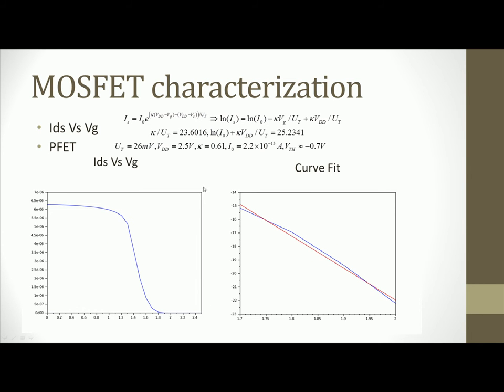For the PFET, it's the same case. We expect that the PFET subthreshold area is like 1.7 volt to 2 volt. And we can also get the threshold voltage of minus 0.7 volt.